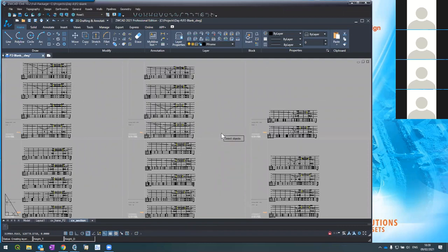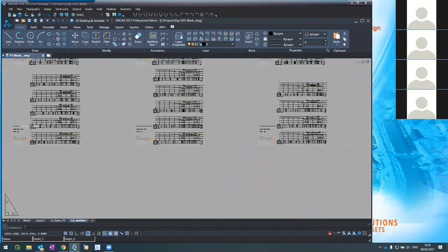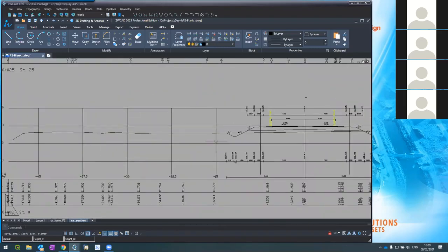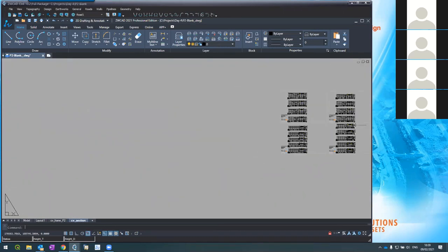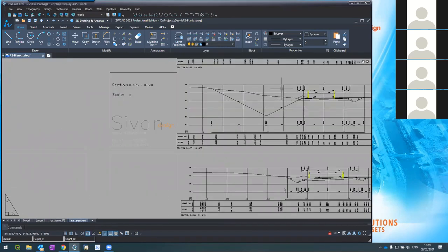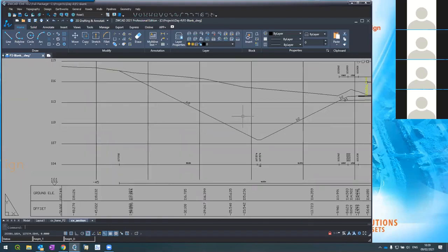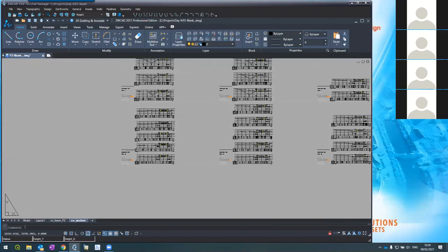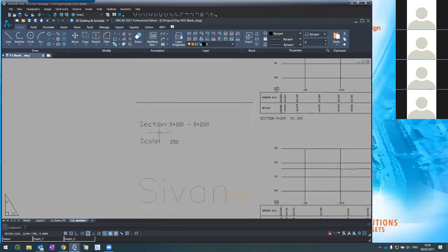The software automatically defines the number of sections on the division by the width of the sections. This is quite a wide section because I set it at -40 to 40 because of the ditches that I have here. So for each plot like this, I have the sections and the scale.